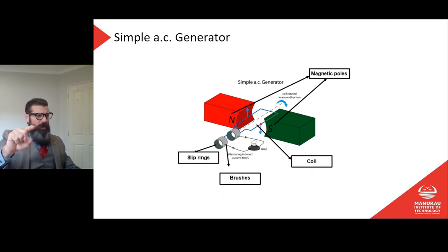When it goes out of the magnetic field, when the coil's not in the magnetic field, it'll be at 0, and then as it comes back in, we're going to see it slowly rise and peak again, but on the other side, the negative side, and that's what gives us our sine wave. The sine wave is just describing essentially the coil moving through that magnetic field from outside the magnetic field through the most powerful part of the magnetic field, out of the magnetic field, and then back on the other side again, so we get a nice positive and negative peak and that sine wave that repeats.